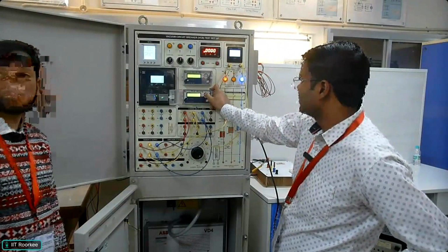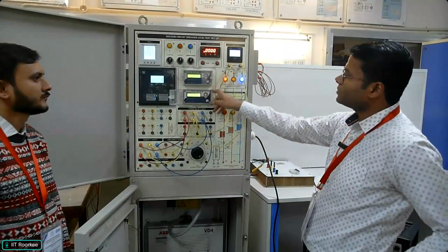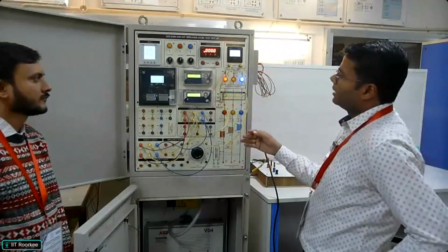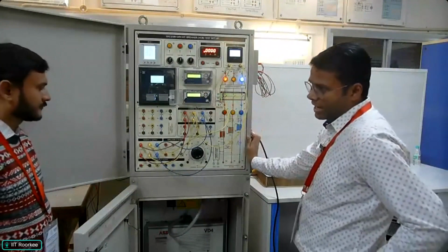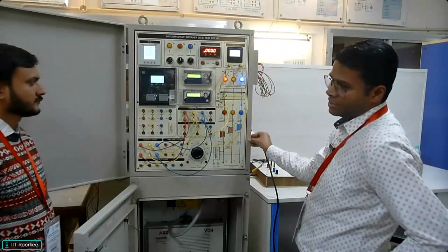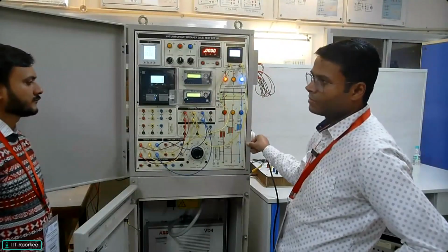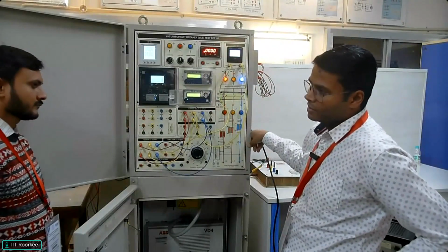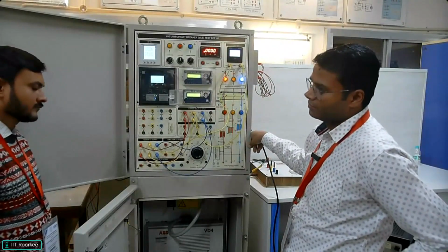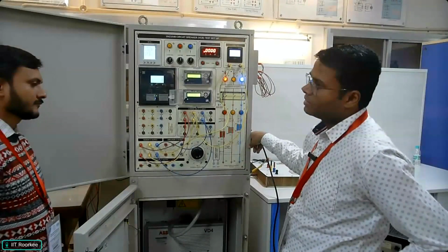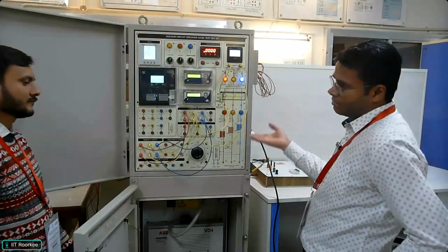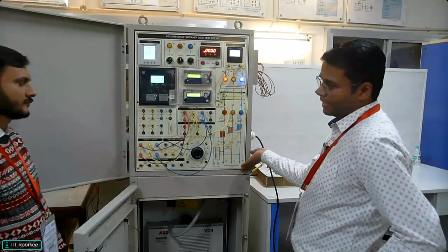So what operation are we doing here? Our CT ratio is 1 and the plug setting is 0.20 multiplied with the CT secondary current, which is IR equal to 5. So our base is 1, and we will see the fault current divided by our primary pickup current.